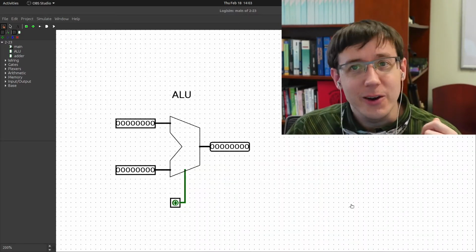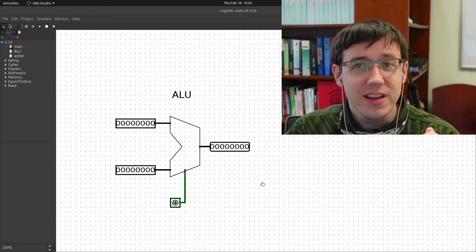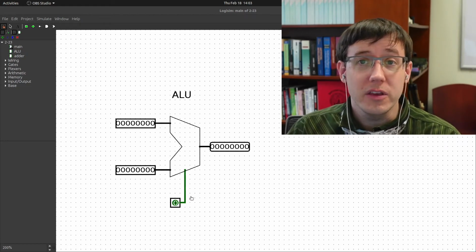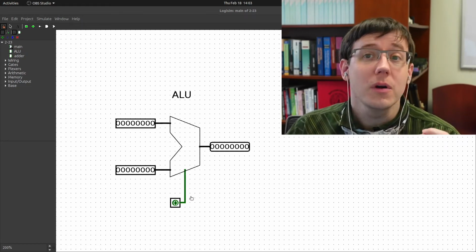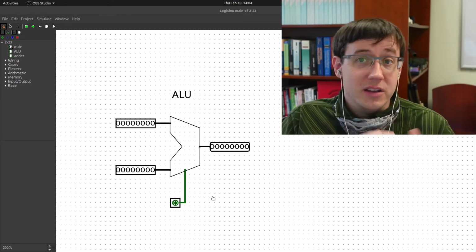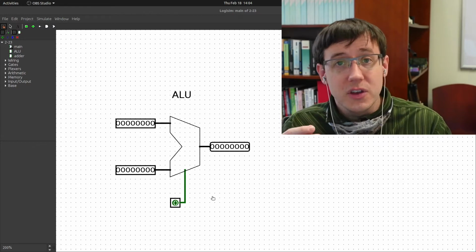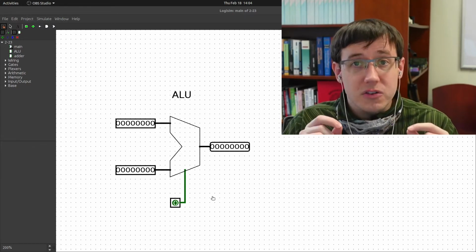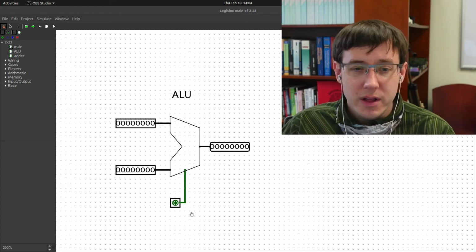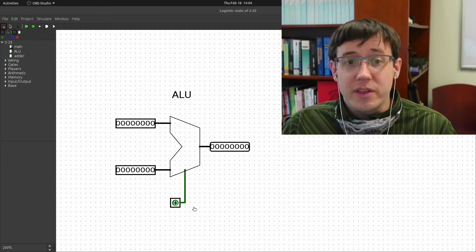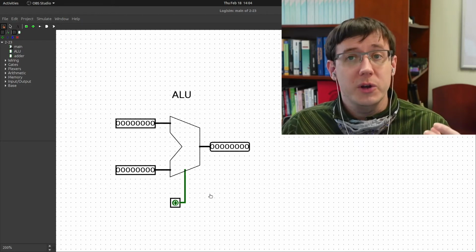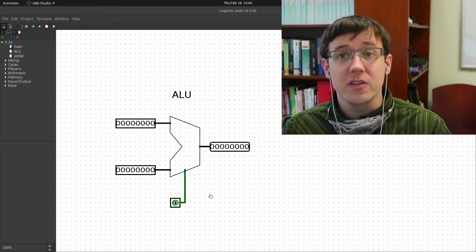While editing, I realized that I had forgotten to mention that this opcode corresponds to the values that your assembler program was outputting. When we translate an assembly instruction into hex, some of the bits of that hex code correspond to the opcode that will be fed into the ALU to determine which arithmetic or logic operation the ALU is performing.